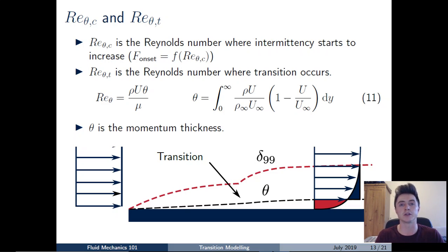Just a reminder from aerodynamics, which you may have come across before: if we have a boundary layer developing over a flat plate or an aerofoil, as you can see there in the diagram, we develop a sheared velocity profile. And for some reason, we may want to replace this sheared velocity profile by an appropriate uniform flow profile.